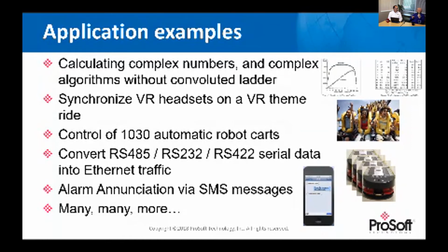Oftentimes we're offloading ladder operations, and I have talked to customers who built ladders with a special algorithm that actually take minutes to run, and in the LDM it takes seconds, even milliseconds to run, because you're running compiled code at the machine language level on the processor. And of course, since you have access to the backplane, you can move your data back and forth very, very quickly, and that solved a lot of problems for people.